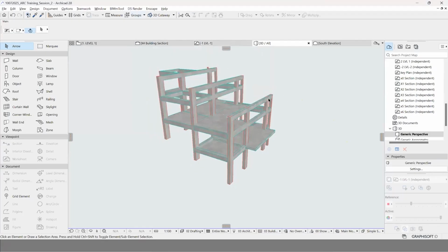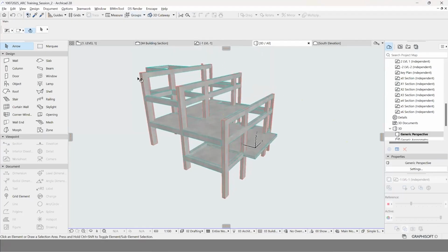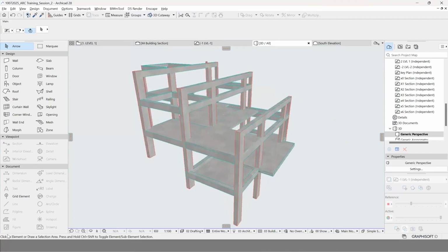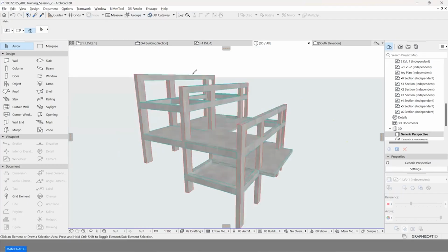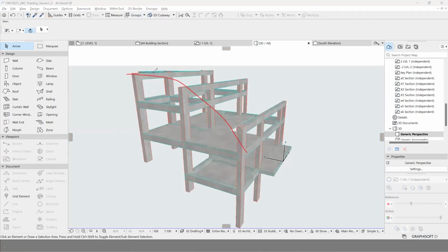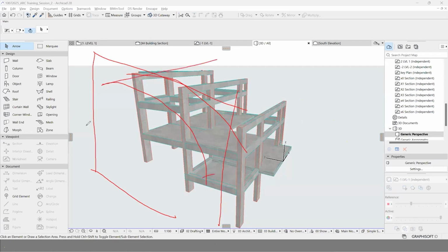Okay. So moving further, this is what we need to create. We need to create an arc structure, more or less like this. When it comes to an arc structure, and it is even a custom profile that we have to create, ArchiCAD understands it in this way: you need a plane to work, a working plane. On that working plane, you are going to draft, and that is going to be extruded. That is the language it works in.